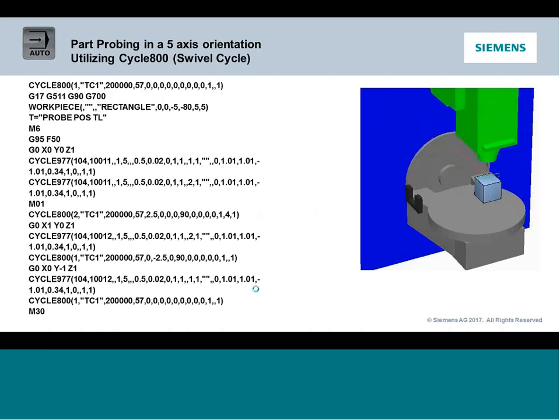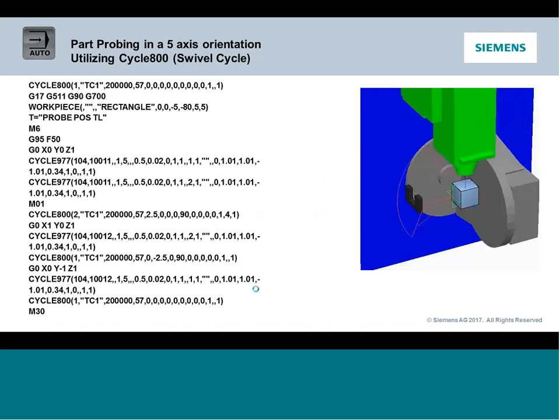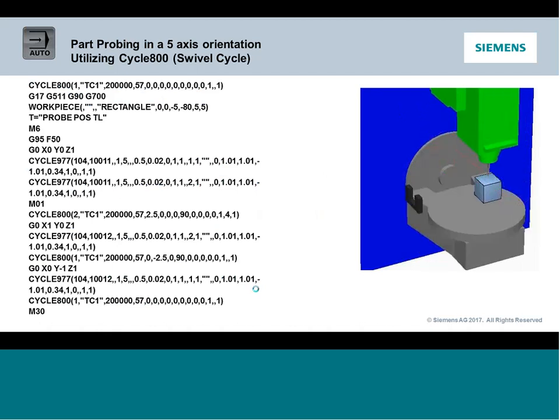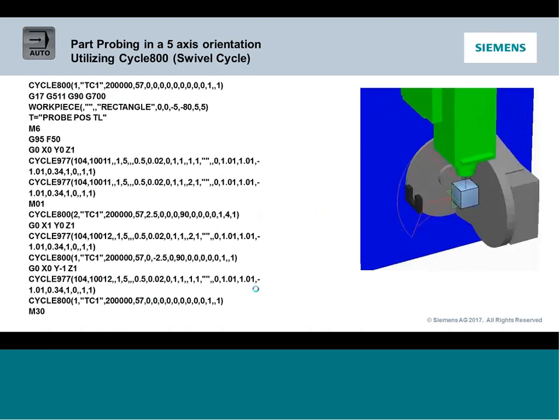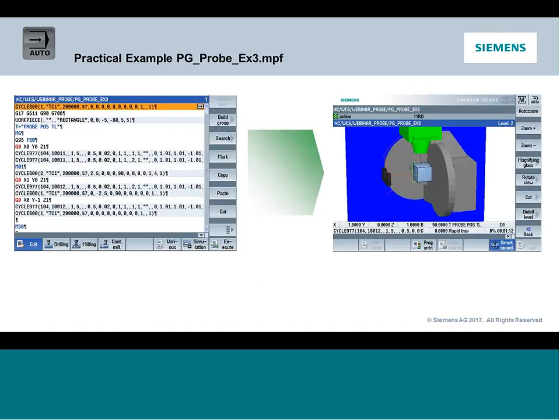So in this little example, I just set a work coordinate from the top and then swing her 90 degrees and set both those same two axes, my X and my Y. But I'm now tipped around. Maybe you've got a case where you can't take the measurement from the top. There's something obstructing you. You've got to tip it from the side. Or you've got one of those compound wrap devices and you want to measure relative to that. You can do that, and it's going to write the appropriate offset as if it was sitting in G17. So we're going to take a look at the source program and then see what it's doing to the offset table when it's all said and done, and how it's deriving the same numbers.